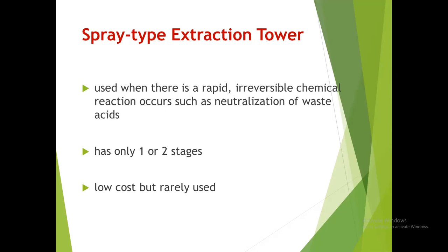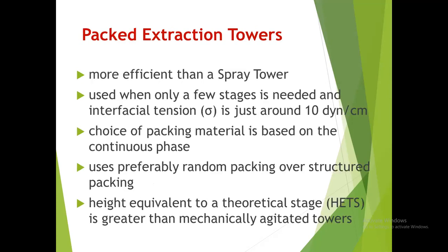Spray extraction towers are not as tall as packed extraction towers because they can only have as much as 1 or 2 stages. So oftentimes 1 stage only. It's low cost, but as in special application only, so it's rarely used. So we have the packed extraction towers, which is oftentimes used because it's more efficient than the spray tower.